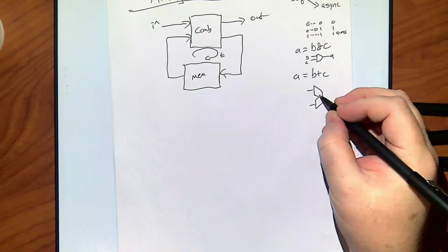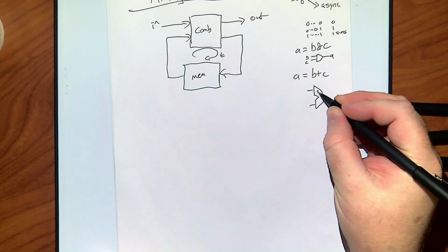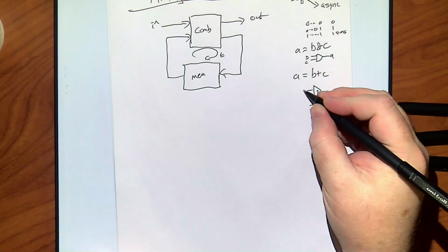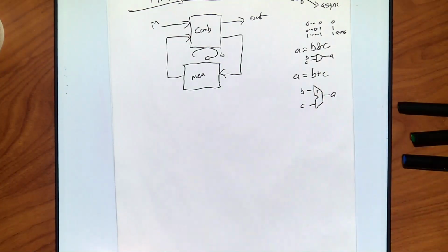what some of the trade-offs are. But for instance, this general symbol, if I don't write anything in it, is an arithmetic logic unit. Right? And in this case, I've got B or C coming in and A comes out. If I put the plus in there, it tells you it is a specialized arithmetic logic unit called an adder, which is just an arithmetic logic unit that can only do addition. So that is completely inferable. We know what those designs mean. We can make libraries with them, things of that sort. It can infer them and go on.